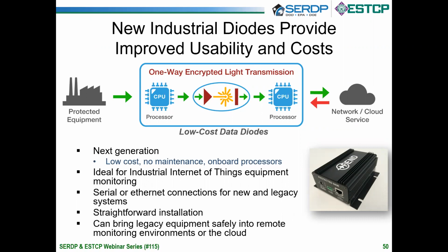Allows us to then bring large volumes of building automation systems and others into remote monitoring environments and really prioritize where to spend maintenance folks' time. These newer devices have serial, Ethernet, and even wireless connections to allow for a variety of different equipment types, including newer equipment that might have an Ethernet port, but also older programmable logic controllers.